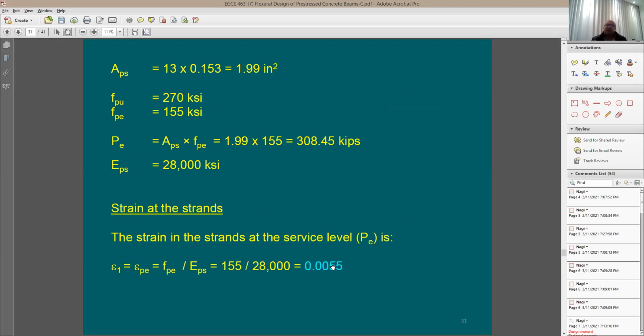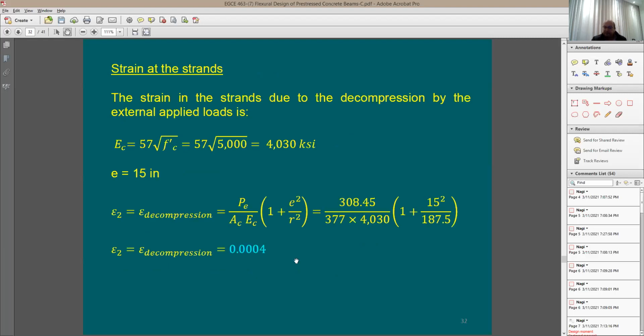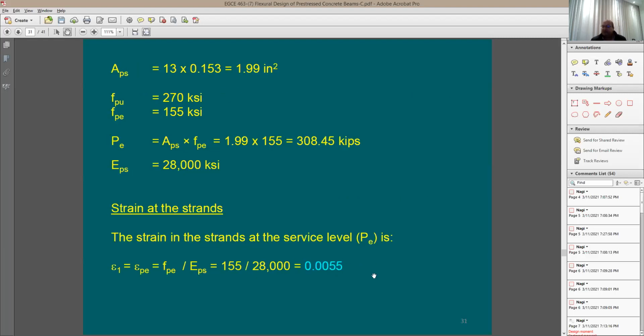And then you look here at the amount of compression that happened in the concrete. At the beginning, you think that strain in the concrete is going to be the strain in the strand. But this is not true. Look at the big difference between the two. How many times bigger? At least 10 times, am I correct? Right? Yes. Now, if you'd like to understand this in a simpler way, you say, let me assume here that I'm going to have a rubber band, just a rubber band.